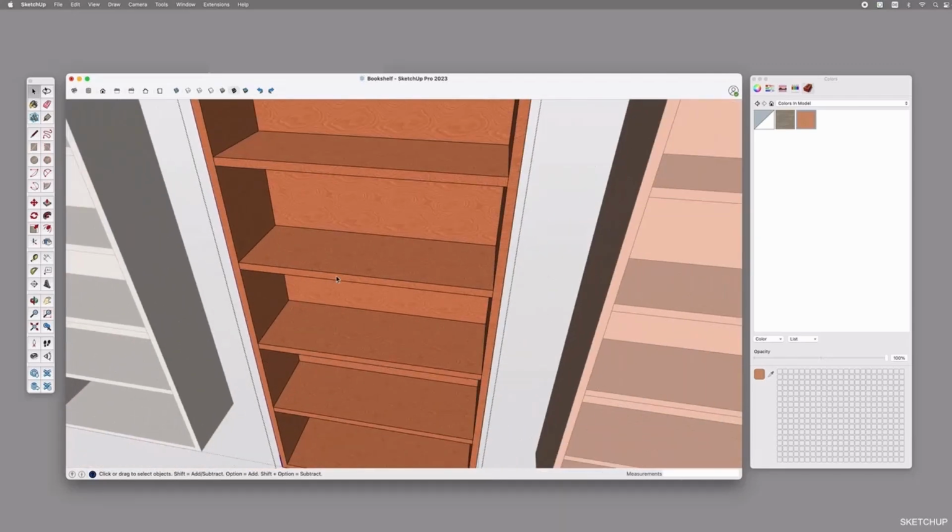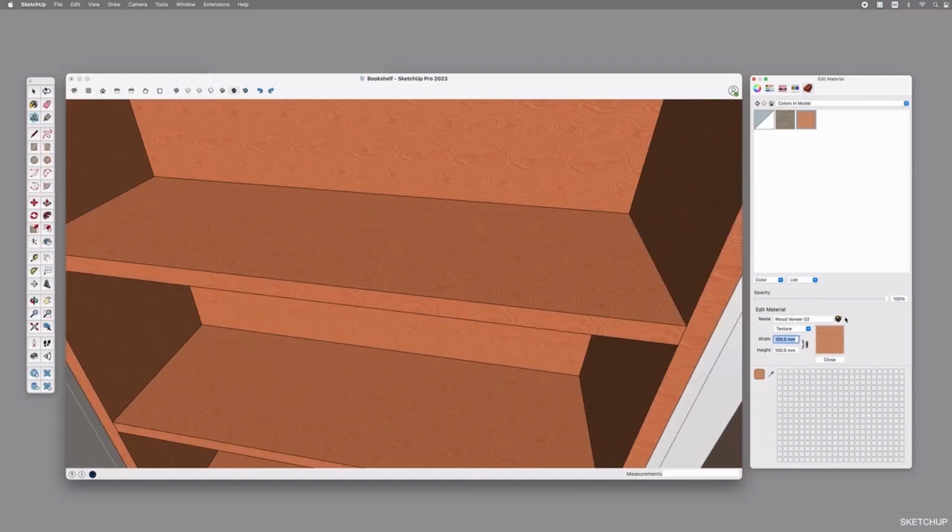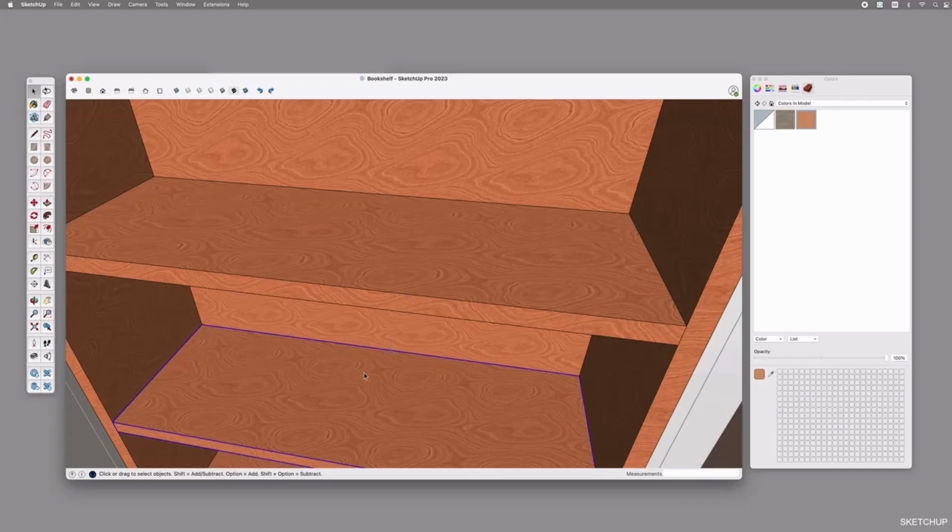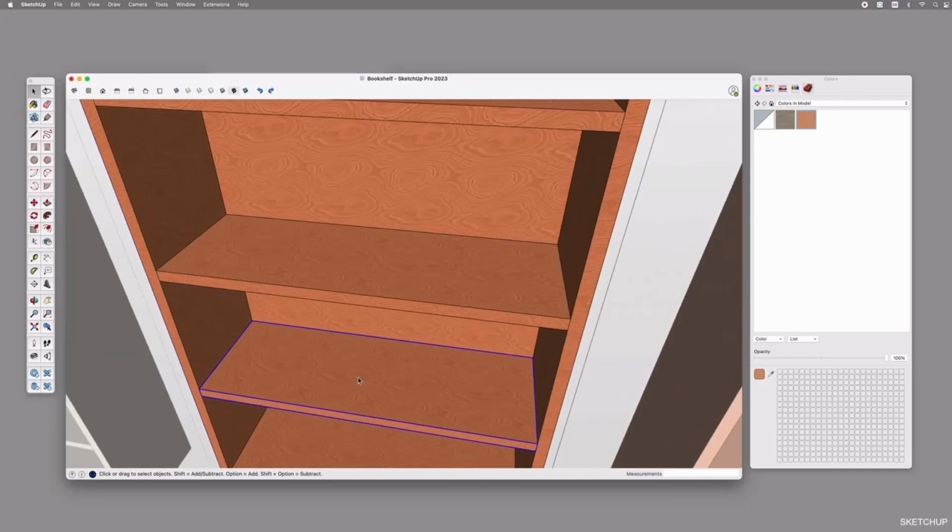Keep in mind that if you make global changes to the scale after adjusting your pattern, the scale will change again once you make subsequent modifications. It is advisable to first choose the texture's scale and then adjust the position of the texture if necessary. In the next video, we will explore how to find more textures from the SketchUp warehouse.